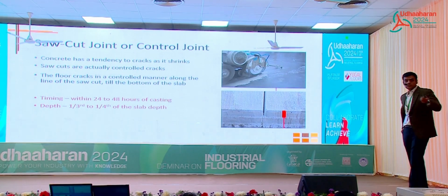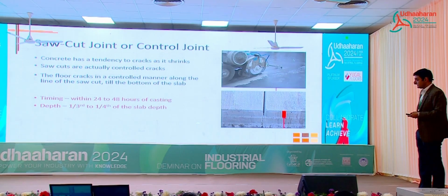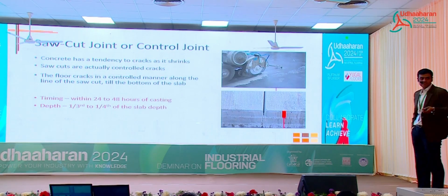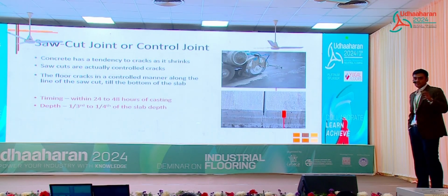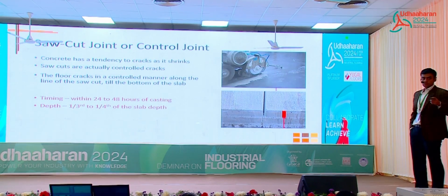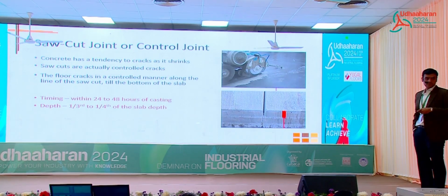So if you see like 10 or 20 meters of crack in the floor, random cracking, you should not panic, because there are already 5,000 running meters of crack there, quite nicely hidden. So what is important is timing. You should do your groove cuts between 24 and 48 hours, and the depth should be 1/3 to 1/4.